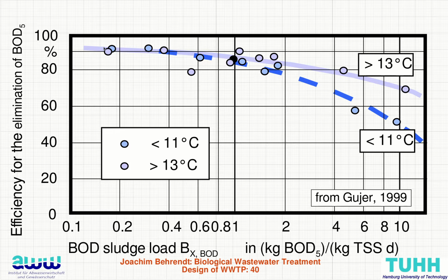And here this is really high. And from this there's a data, also 0.3 is compiled. If you want to have stable BOD removal, there you have also some reserve, or 0.05 if you also want to have stable nitrification.